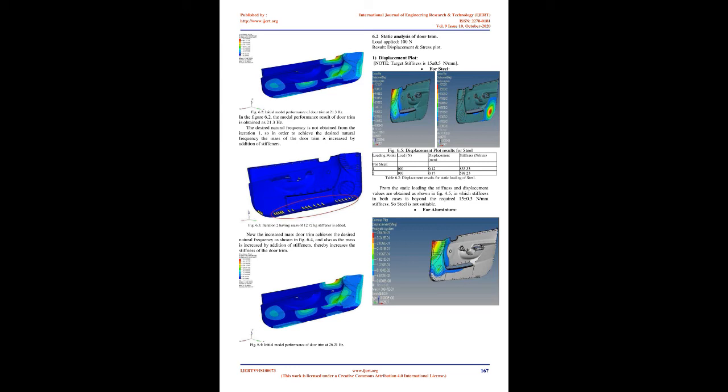C. The 6 degrees are 3 translations and 3 rotations. D. The property of a rigid element is to constrain the region so that it does not get any displacement or stress. E. A rigid element adds stiffness to the original structure, except RBE3. F. RBE2 distributes force and moment equally among all connected nodes irrespective of the position of force or moment application. G. RBE3 is a constraint equation that distributes force and moment as per distance.